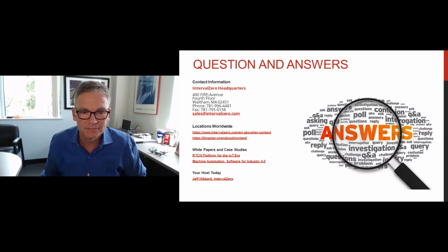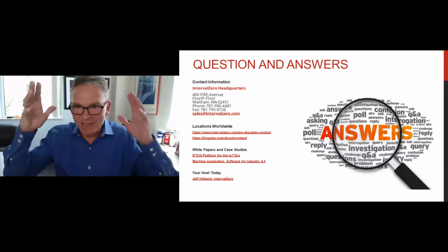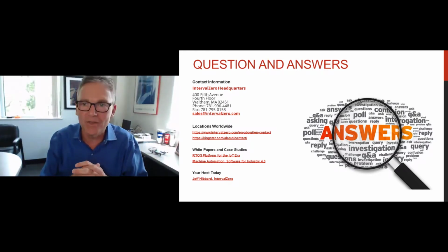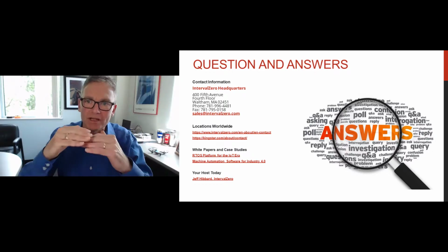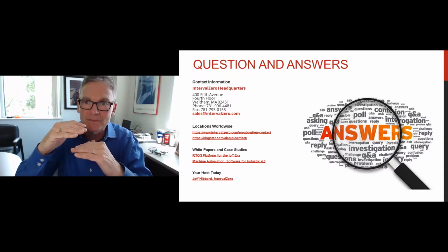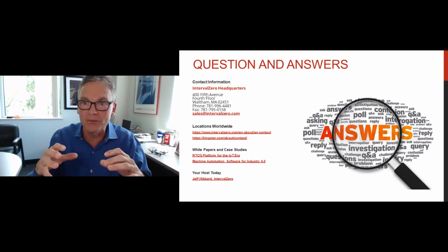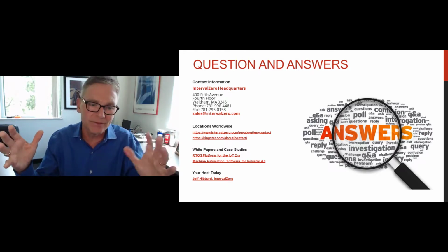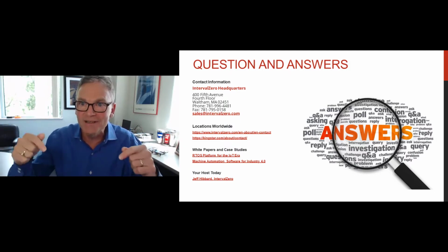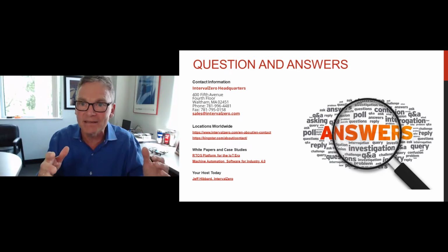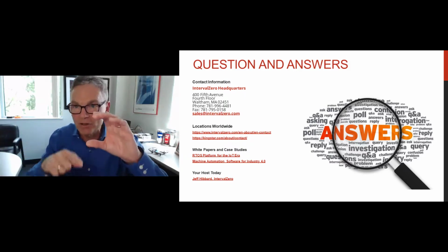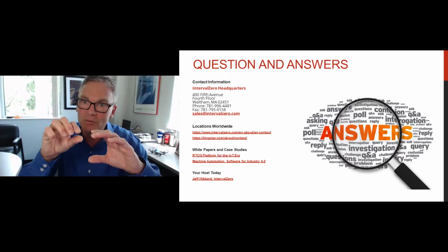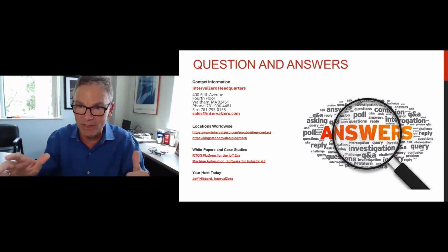You said that TSN is used in the machine controller context, but where else can it be applied? Okay, so yes, we're machine automation heads, but it turns out that TSN is a collection of standards that prioritize many protocols. TSN right now is being used in a lot of automotive applications. You've maybe seen that there are a lot of chip shortages, and cars are not being able to be made. The reason is that your car is kind of like a rolling computer, and TSN is being used as the network inside. What you want is quality of service, so different readings and different messages on the same backbone can be delivered.